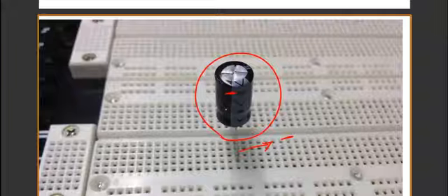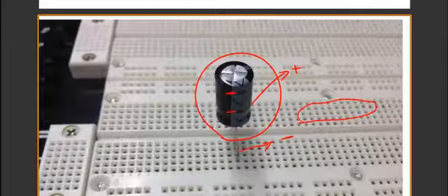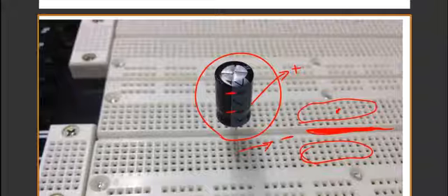They are marked as negative, and the other side, which is a pin that I have put on the other side, one of the holes above this gap, is the positive one. Please make sure that when you put the polarized capacitor, one of the pins is in this area and the other pin goes on the other side of the area. So they are separated by this gap here. So one pin goes here and then one pin goes here.